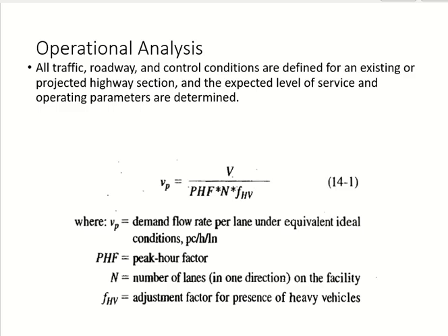You have to check if that lane is extra for some specific turning. Then you need to see if it is continuing. If it continues from start to end, then you count it. If it is just near the intersection, say 100 meters before the intersection, the lane comes, this is separate.